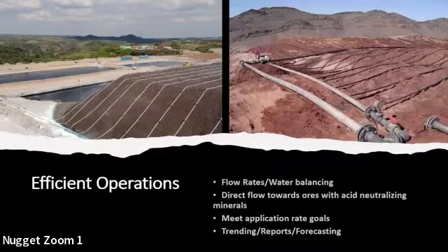This graph has the saturated hydraulic conductivity on the y-axis and the PSD indicator increasing on the x-axis. The benefit is that if you're able to easily acquire physical measurements, in this case particle size distribution, you can calculate the PSD indicator. For this particular ore, this yellow line right here is the 100x safety factor, so you want to be above that yellow line in the white zone.